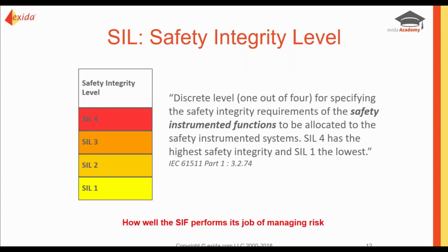In not only IEC 61508, but IEC 61511, it defines SIL as your safety integrity level. And there are 4 SIL levels, 1 through 4, 1 being your lowest, where 4 is your highest. With each level, there are more requirements and more justification needed to prove that you are at a higher level. So every time you move up a SIL level, you not only need to do the requirements from SIL 1, you need to add extra SIL requirements for SIL 2, and so on, until you get to your highest level,